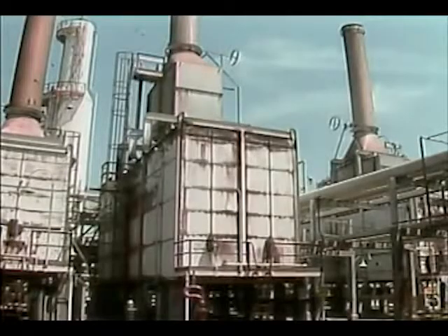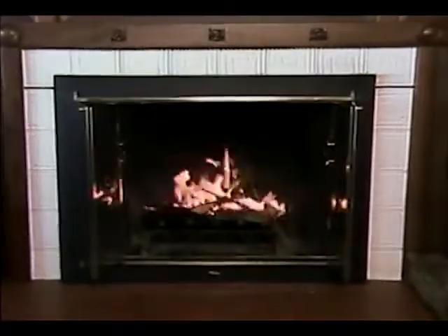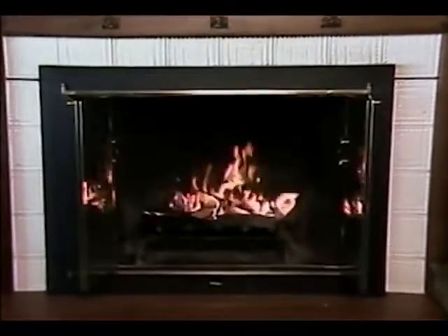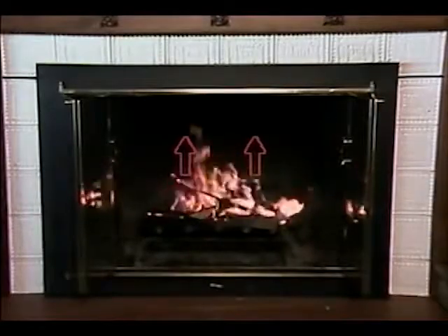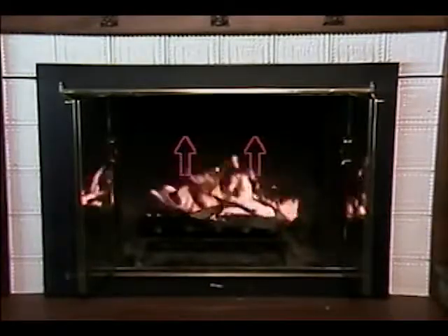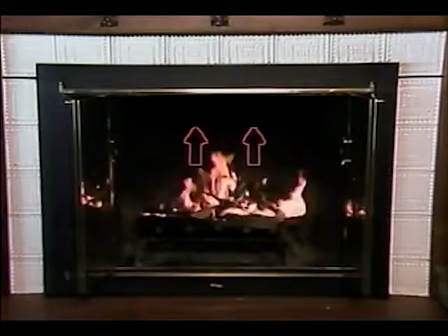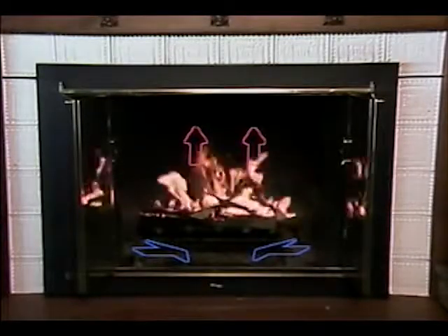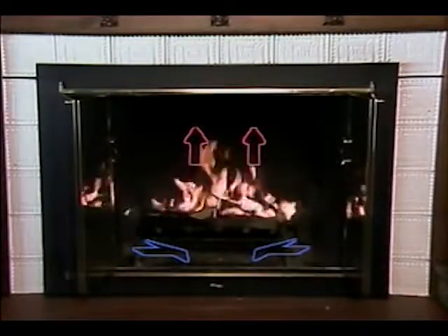A natural draft furnace works much like a fireplace and a chimney. Heat from the fire in a fireplace warms the air in it. The heated air in the fireplace is lighter than the cooler air outside, so it rises through the chimney. This reduces the pressure inside the fireplace. As the hot air rises, it's replaced by cooler, heavier air in the fireplace, and the process continues.